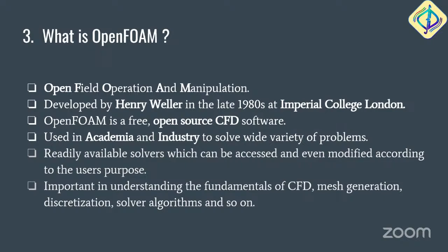You have multiple options as well. Unlike ANSYS, where you are restricted to a very select set of solvers, and if you have to modify something, you don't really know the backend code. But in OpenFOAM, you do have that privilege. You can modify the solvers based on your application. Suppose I have a heat transfer case and I want to introduce another factor into it. I can open the backend code, modify that, and create my own solver. Those privileges are there in OpenFOAM. And if you're starting off with CFD and you want to learn the physics behind CFD, not just clicking buttons, OpenFOAM is good that way because it helps you understand what boundary conditions you're putting.